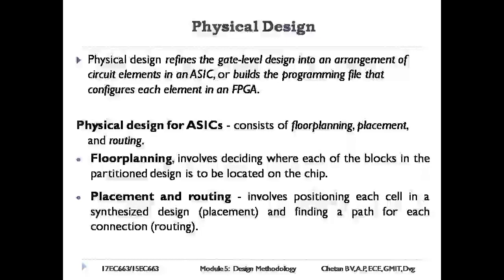Detailed timing information is generated based on the actual position of components and wires. Detailed timing simulation is a final check to ensure the design meets its timing constraints. Placement and routing are automated by EDA tools.